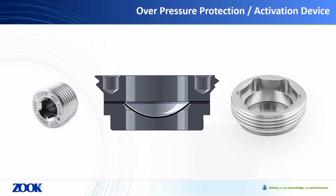There are, however, some other value adds to a rupture disc that I haven't mentioned. Rupture discs are traditionally lighter and faster acting than a relief valve. In truth, the rupture disc is not only fast acting, but it instantaneously allows full flow, all the way up to its specified relieving area. This ability opens the door to some other uses beyond overpressure protection.